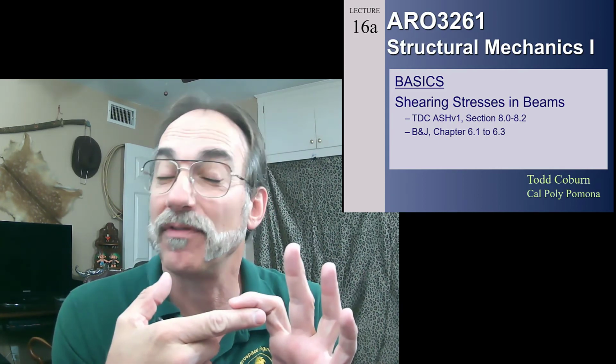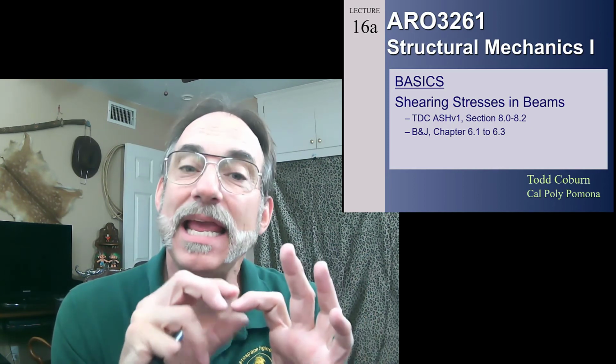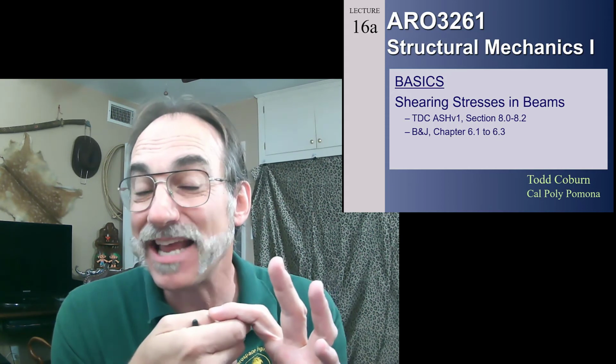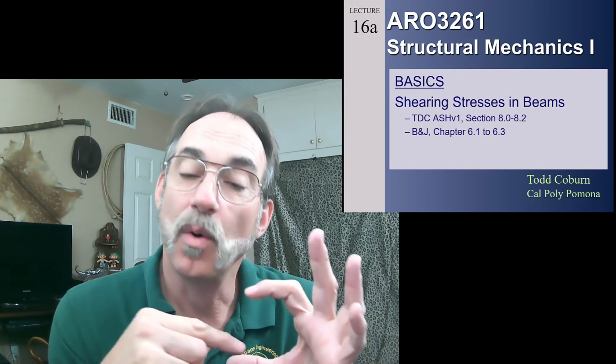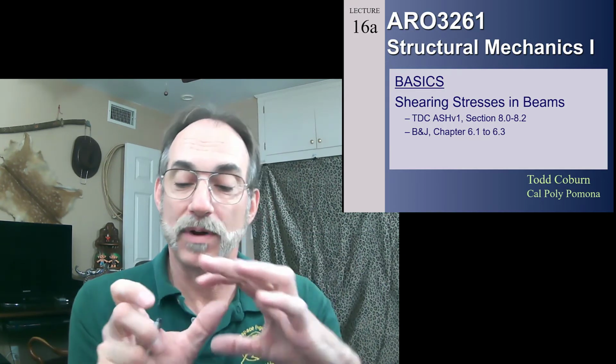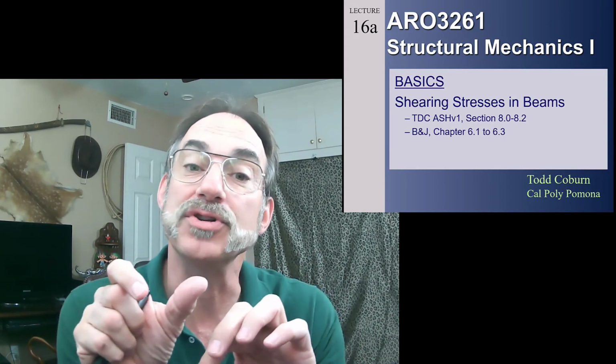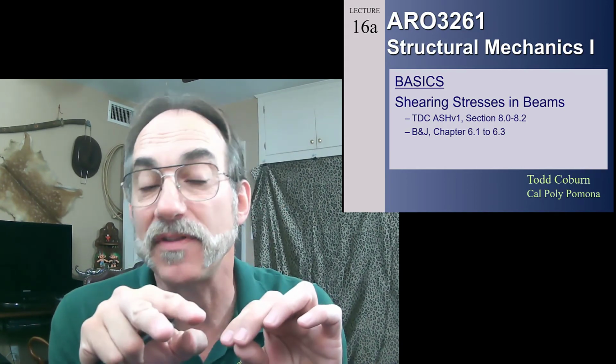But today's lecture not only will teach us about shear stresses in beams, we'll learn a little bit about shear flows in beams, and then the very important topic of being able to figure out, using these same formulas, how much shear will be in a fastener that's holding pieces together. Like if we nail a couple 2x4s together, what is the force in the nail? Or if we have an I section on an aircraft or a J section that somebody then goes and rivets a strap to the upper cap to beef the thing up. How do you calculate the force in that fastener?